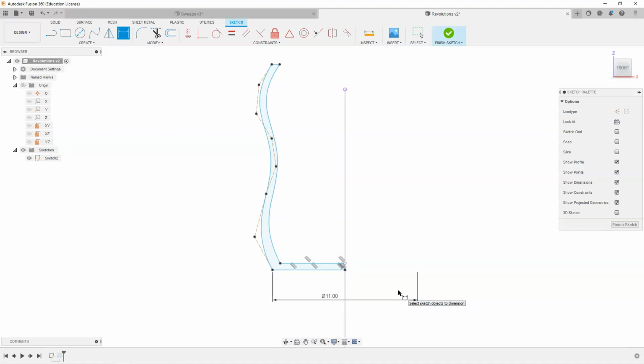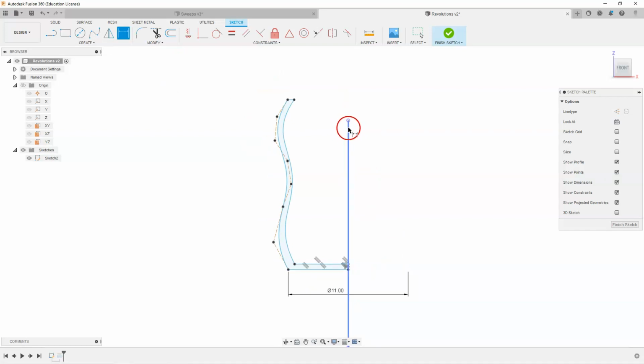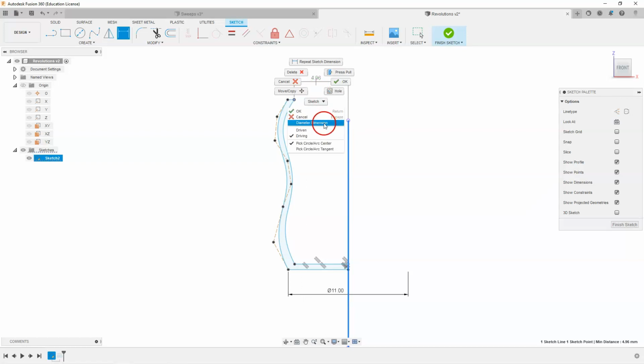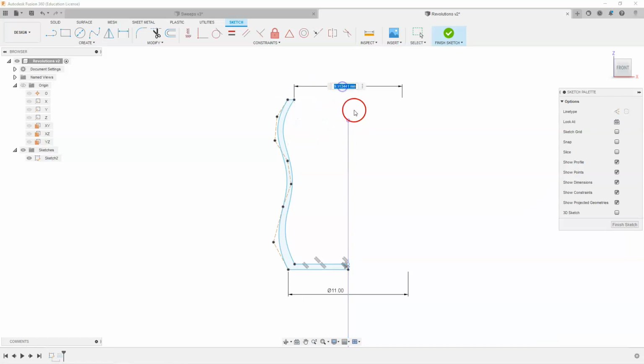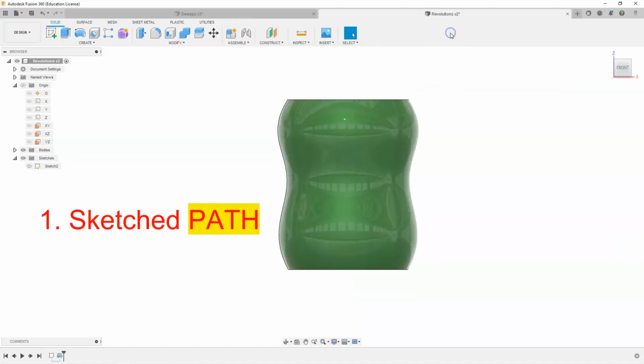It's more proper to show a diameter on something round than a dimension from the center line to the edge. So demonstrate that at the top. Select my axes, select my other point up there, right click, diameter dimension, and I put the diameter dimension in there. I'll make that nice and simple, 9.9.